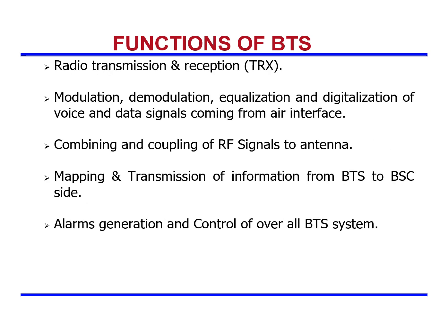Functions of BTS. The first function is radio transmission and reception done by the TRX card. Modulation, demodulation, equalization and digitization of voice and data signals coming from the air interface. Combining and coupling of RF signals to the antenna. Mapping and transmission of information from BTS to BSC. Alarms generation and control of the overall BTS system.